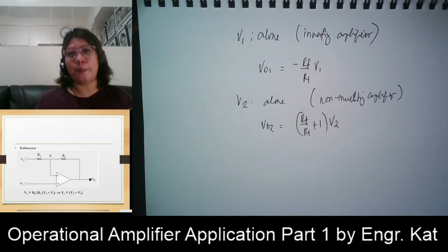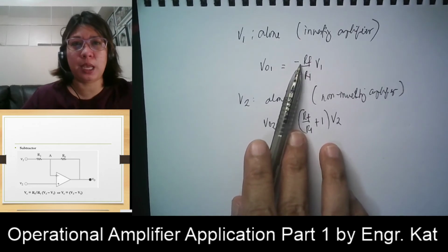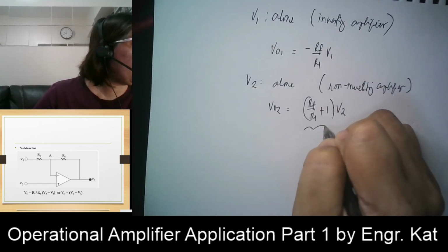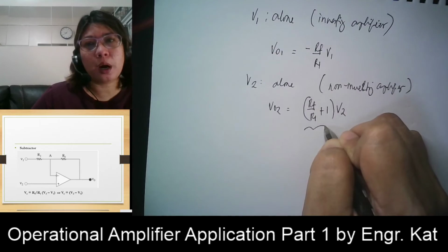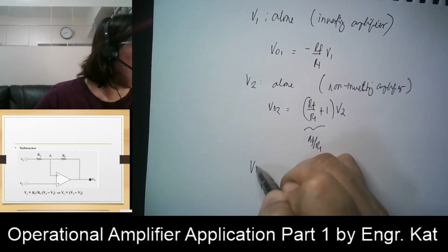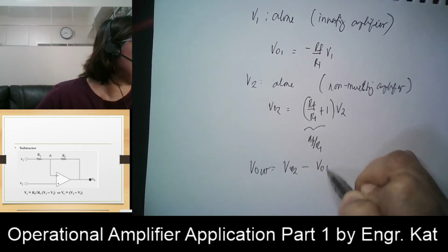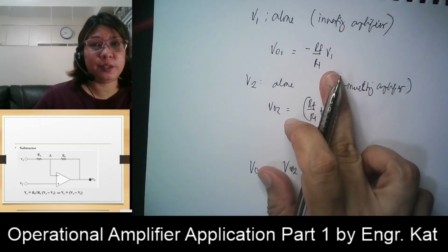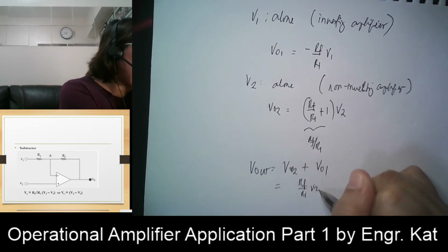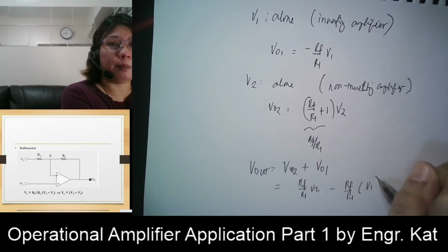We're going to either add them or subtract them. But since this is of negative sign, if we add them, we will be having a negative sign here. For simplification purposes, we can just assume that RF all over R1 plus 1 is approximately equal to RF all over R1. Combining the two, your V out is equivalent to VO2 minus VO1, because of the negative sign there. So VO2 is RF all over R1 times V2, minus, because of the negative sign, RF all over R1 multiplied by V1.